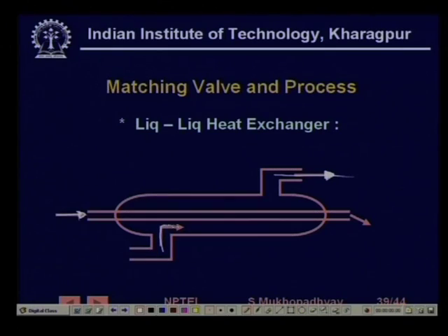When the flow rate is low, the liquid stays within the tube for a longer time, and therefore the gain is higher: for a given rate of flow of the heating liquid, the increase in temperature between the inlet and the outlet will be higher.